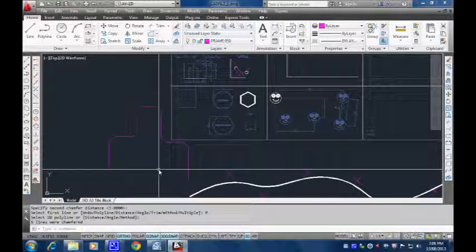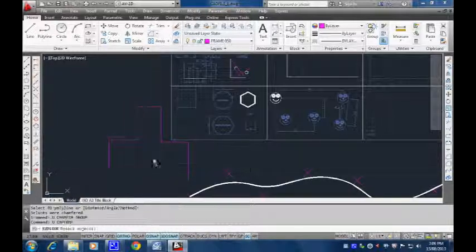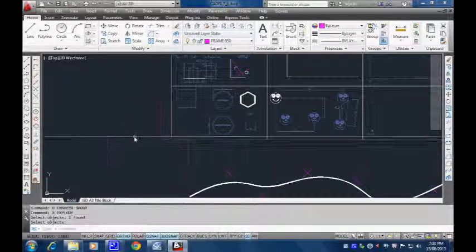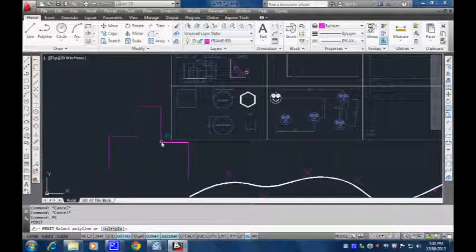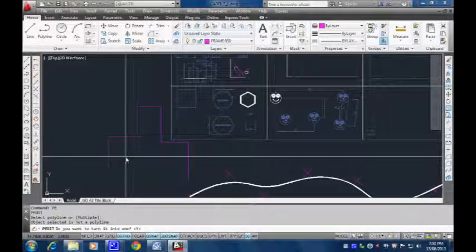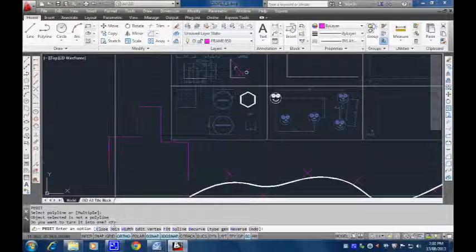If this wasn't a polyline already, and it was a bunch of lines, remember that command we had before, PE, that we used for the width and whatever else, we can use PE again. We had the fit and we had the spline, and that command, PE, had another option. So click on here. First of all, if I don't click on a polyline, it will come up and say, do you want to turn it into a polyline? It's a stupid question, I know. Yes is always the answer. And then it goes into those lots of little options.